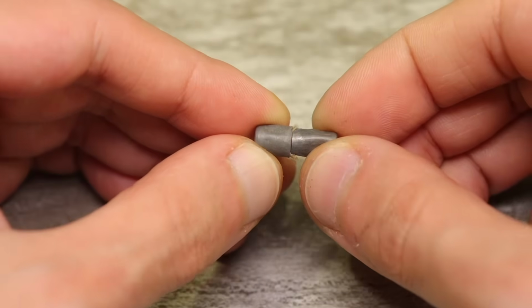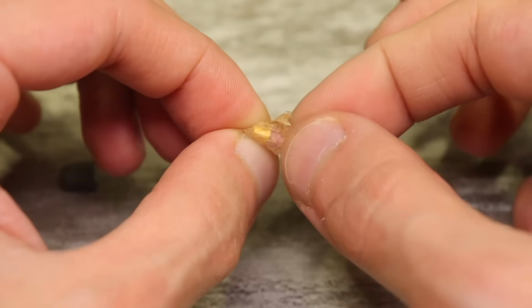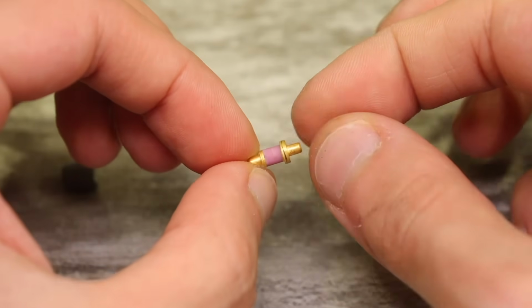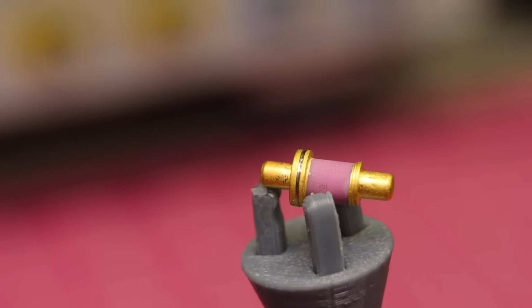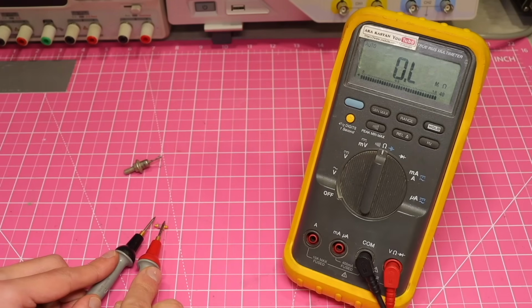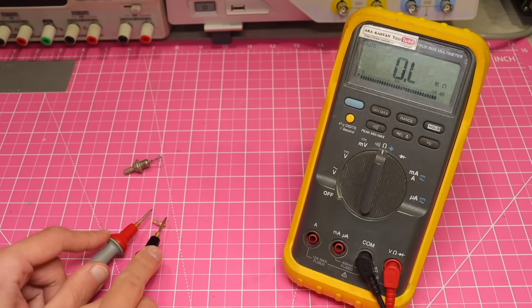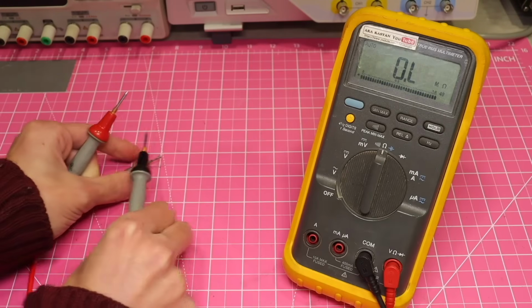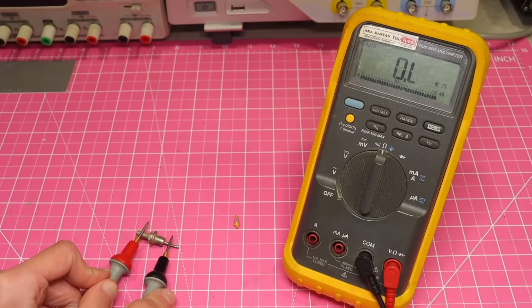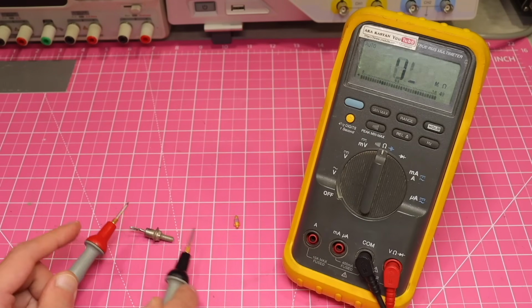Most likely, many of you are hearing about this diode for the first time, and that's perfectly normal. These aren't common components, at least not in household devices. This diode is so unusual that it only has N-type crystals. That's right, it doesn't have a p region. It also doesn't have any barriers. It doesn't rectify anything and doesn't have one-way conductivity like a regular diode. It was created for one purpose: to generate ultra-high frequency oscillations. And sometimes at such high frequencies that even many modern microwave devices would envy it.